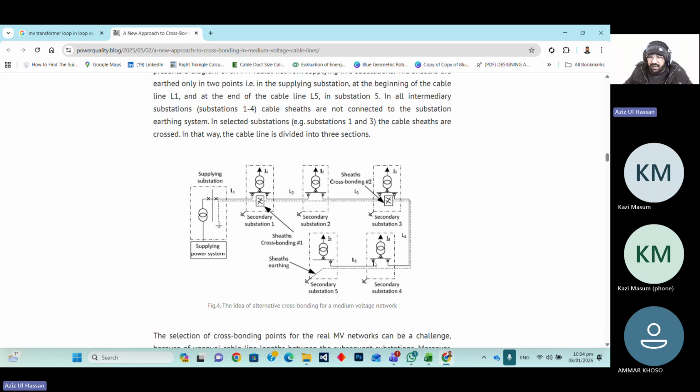So in that cable, the current traveling through it should be 125. Now when this cable goes into that transformer and out of that transformer, two transformers will be connected in parallel, so their currents will add up. Now in that cable, the current should be 250 ampere.